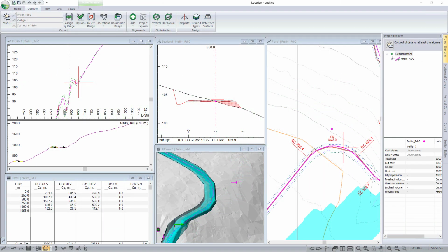In this video we are going to introduce the idea of report points. So report points are a very important part of the location module, the module you're using to design your linear infrastructure in RoadEng. And with that, it's because we use a cross-section model, and report points control how frequently and where those cross-sections are created.